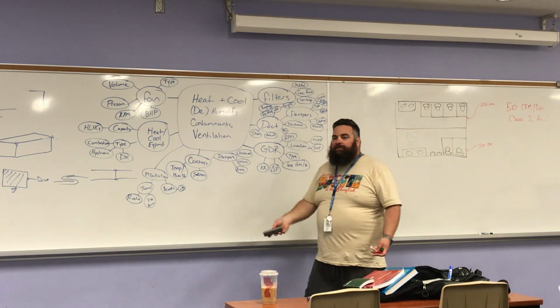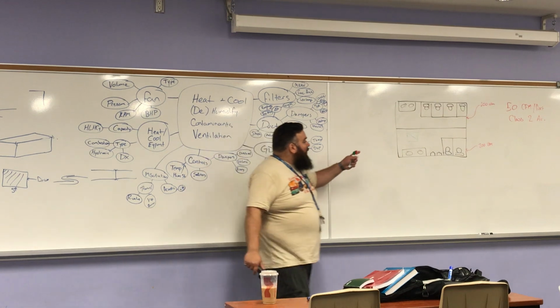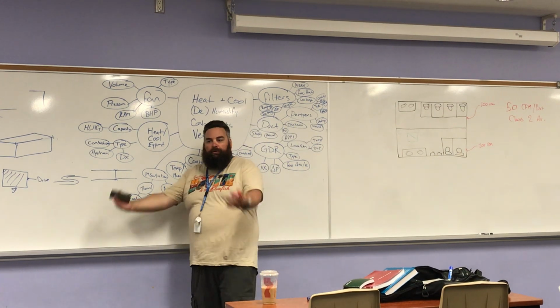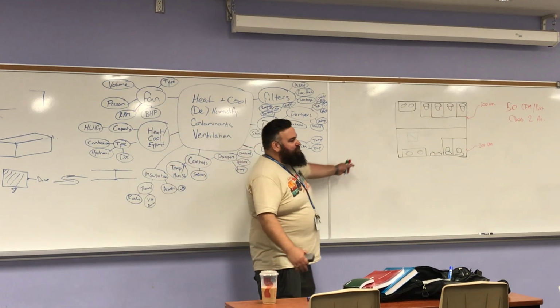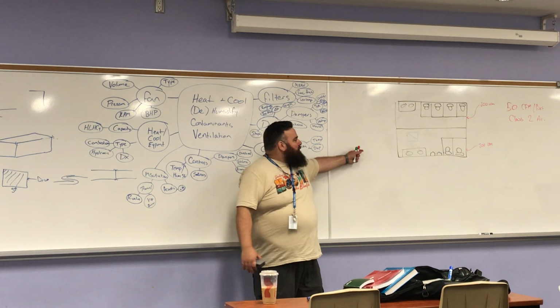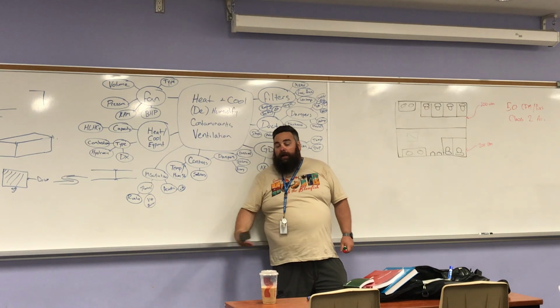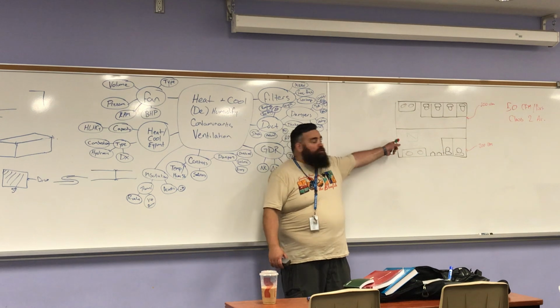I'm trying to exhaust the contaminants, right? I'm trying to do a couple different things. I'm trying to keep this space under constant negative pressure because I don't want those odors or moisture to migrate to the rest of the space. This is not just bathrooms free floating out in the ether. This is part of a larger building. I want to control the odor and moisture where it's generated. I don't want to have it move.